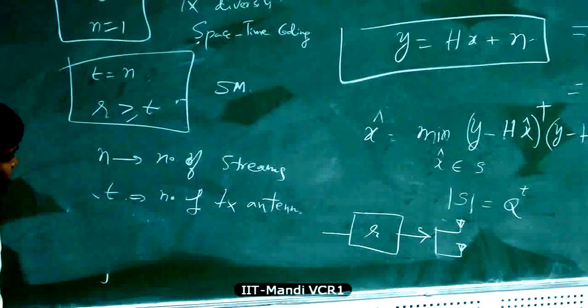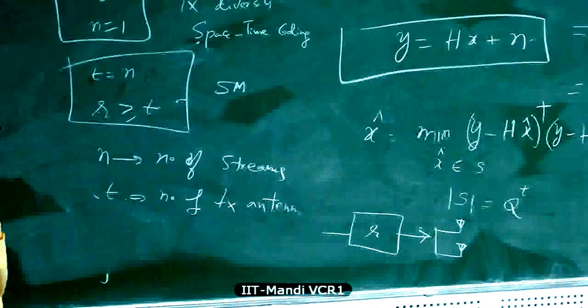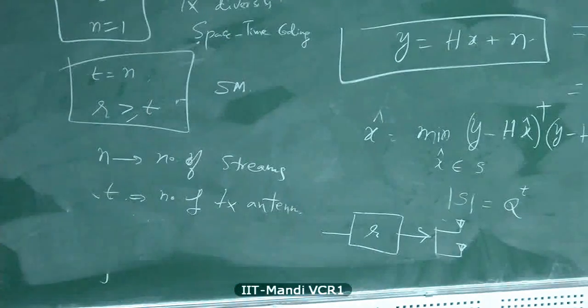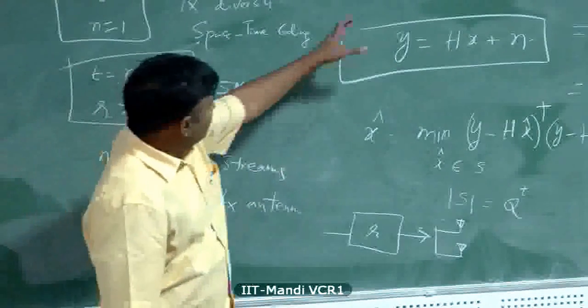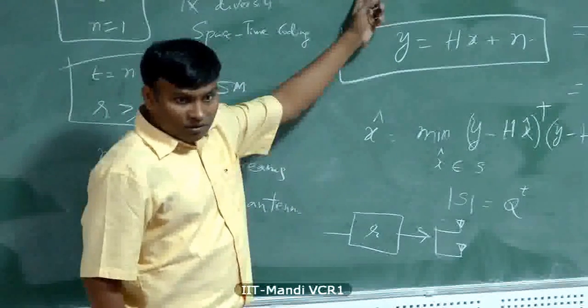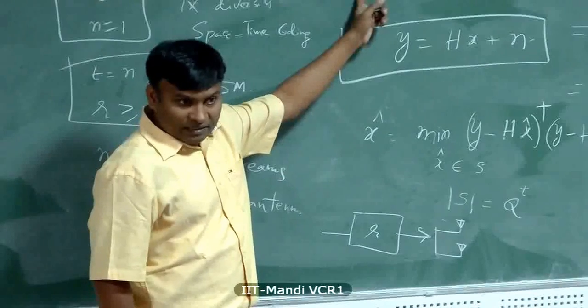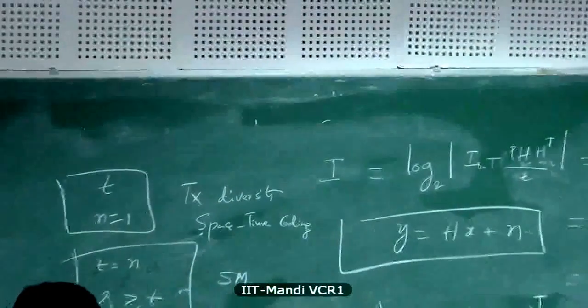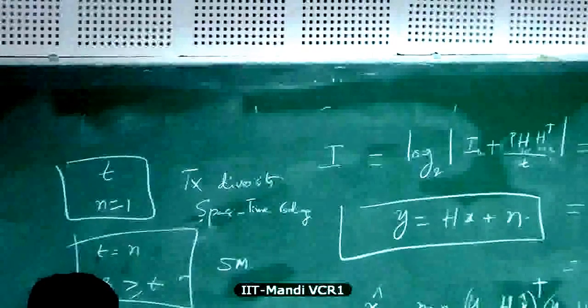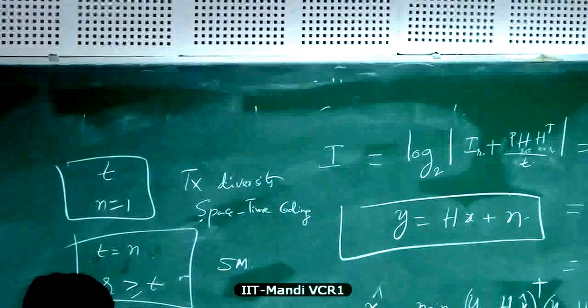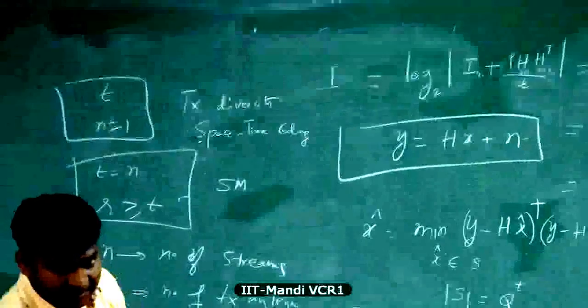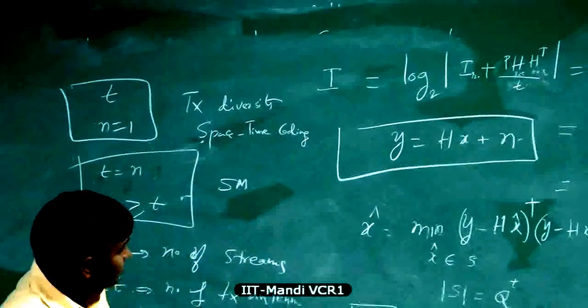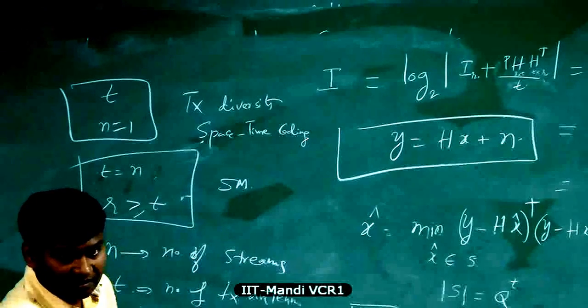Okay, so what I want you to do is simulate the performance of the MMSE receiver with spatial multiplexing, which belongs to the open loop class, and then simulate the performance of closed loop, which is beamforming, with the knowledge of H at the transmitter. That is a fairly simple simulation because it doesn't involve bit error rate calculation. Anything that involves bit error rate, you have to simulate the whole link. But this is simple. So you can simulate these two and compare.